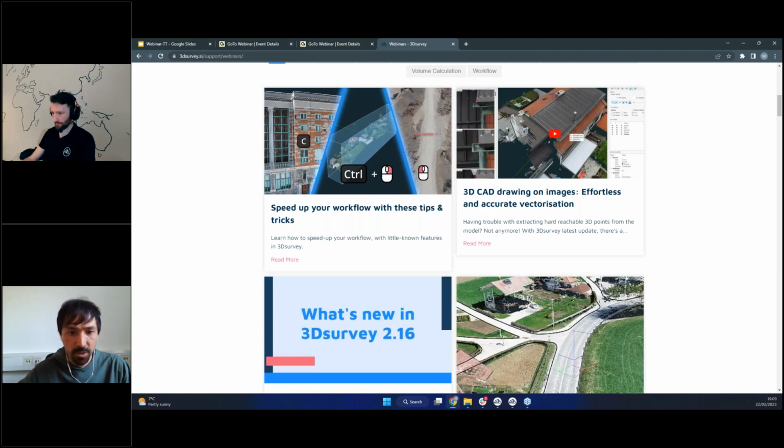Okay, then Achim Fosters is asking, if we fly above 80 meters AGL, what will be the best overlap to get a good result? Okay, so if you go for a standard, traditional orthophoto, 70% overlap is more than enough.